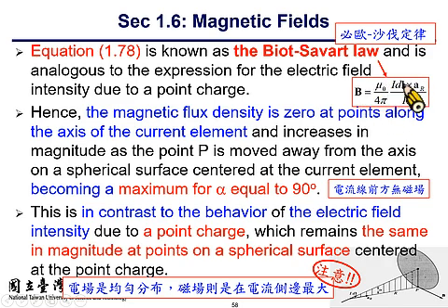And because this is a very short piece of current, it can be regarded as a point source, similar to Coulomb's law. So you have the 4 pi to address its relationship to the surrounding area. And the thing that is different from Coulomb's law is the direction of B is determined jointly by the source position and the observation point, which is addressed by aR. So it's in the cross product relationship. So dL cross aR shall give you the direction of magnetic flux.